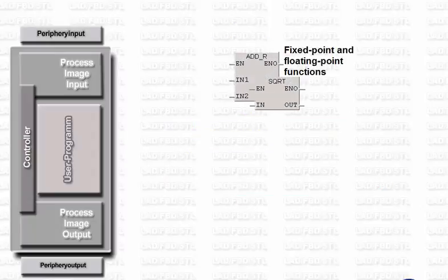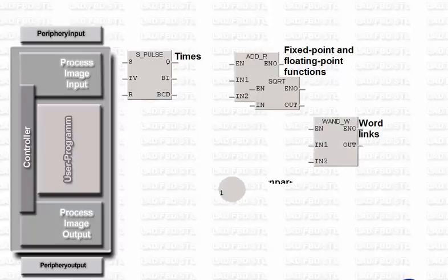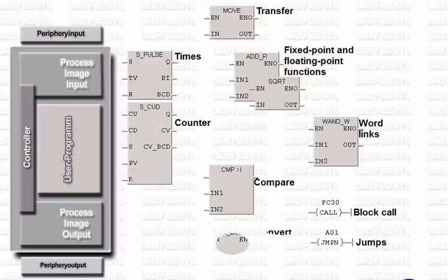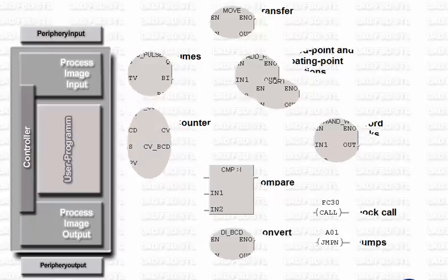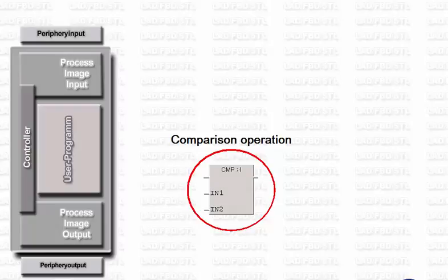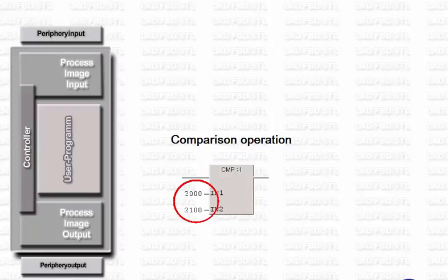But the Ladder can do more than just combine binary signals. It can also be used for effective and comfortable processing of digital values. Ladder offers for this purpose an extensive range of functions which allow you to handle almost any automation task. More complex functions, such as executing a comparison operation, are implemented by inserting a box that provides the required functionality within your program. Such a box can have several inputs to receive input values and provide the result to an output.